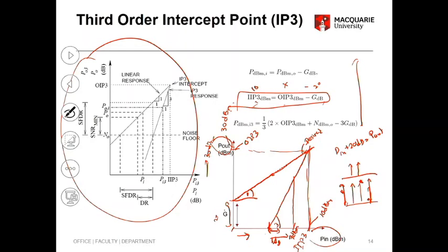Now at 7 dBm, you are, what? How many points are you there here? You are 10 minus 7, that's 3, right? Got it? And that's gradient of 3. So this has to be 9, right? You know this is 30, so this level has to be 30 minus 9, which is 21 dBm. Is that clear? So basically at 7 dBm, you will have your IMD at 21 dBm.